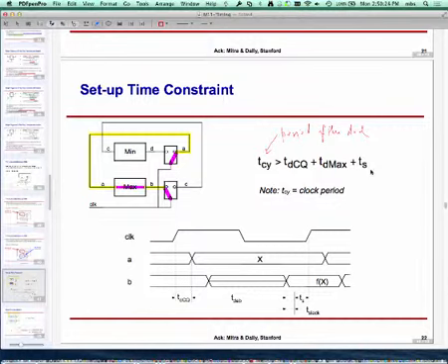If you think of your circuit, there are going to be a lot of pathways in it which start at the output of a flip-flop, go through some combinational logic and end at the input of another flip-flop. So this inequality, you have to look at for each such path, starting at a flip-flop, ending at a flip-flop. You are going to look at propagation delay of the starting flip-flop, delay through the combinational logic, setup delay of the ending flip-flop, in case your flip-flops are not identical.